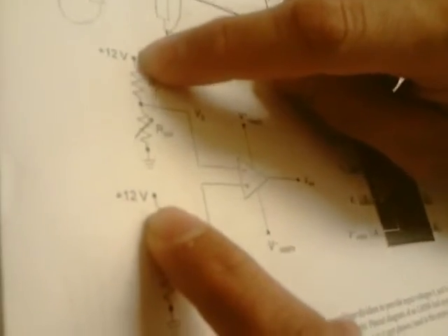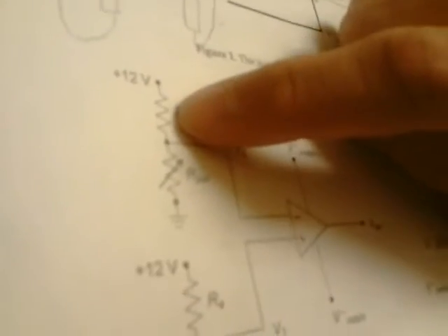The way we're going to create the 2 different voltages is each one has a voltage source of 12 volts, and we're going to alter these resistances to get the voltage that we want. The LDR that we talked about in the first video is going to be this right here in place of the potentiometer. So this voltage is going to be controlled by the light, and this voltage is going to be held constant at around 5 volts.